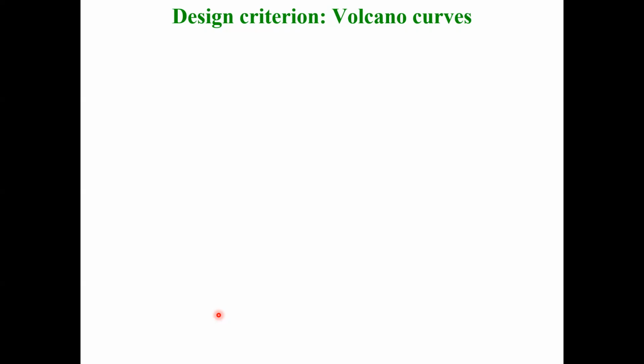When you supply oxygen, what is the first step? The first step is that the oxygen is not used for oxidizing the reactants. The oxygen goes towards oxidizing the metal to metal oxide. So even though you may start with metal, during the course of the reaction, in the first few hours when you run the reactor, the metal gets oxidized to metal oxide, and the metal oxide is the real catalyst.